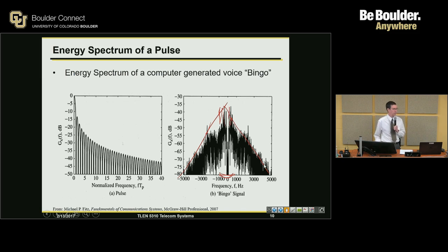And I don't need to transmit the entire thing. The higher frequencies don't have as much information content, so I could probably just filter those off at the end and then just transmit that piece. Otherwise, I'd be transmitting a very long tail out into the frequency domain, which is just not spectrally efficient.